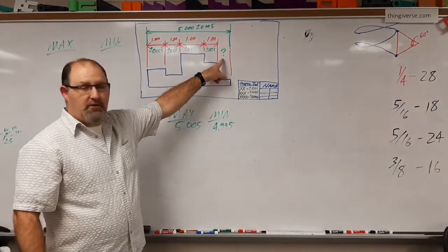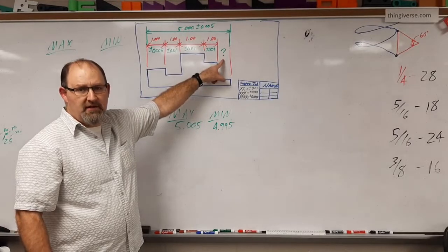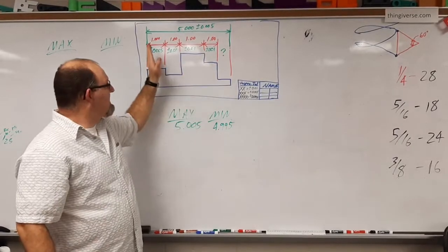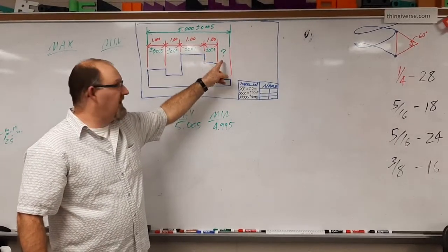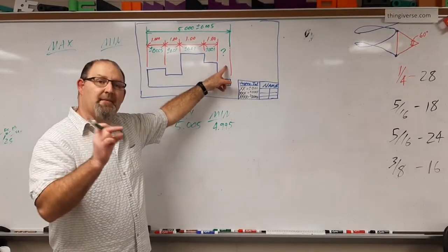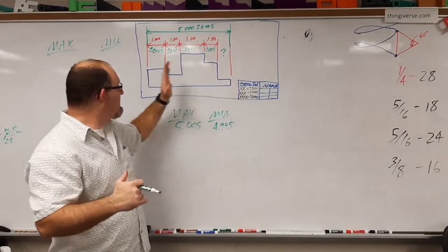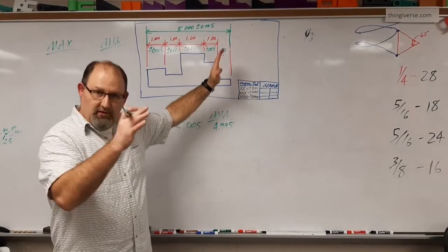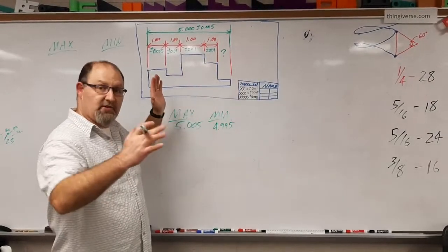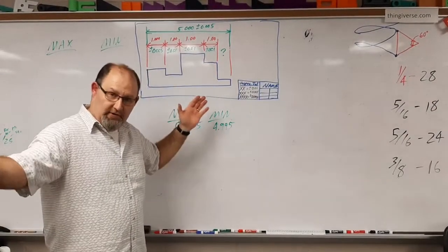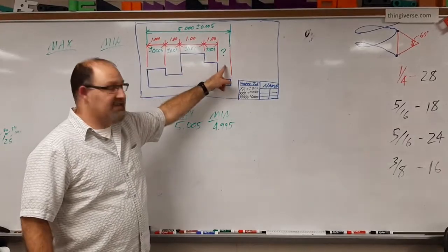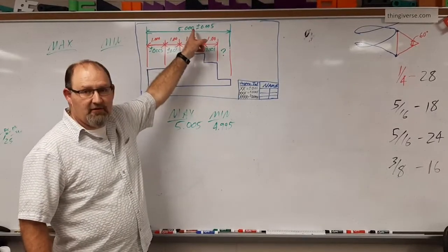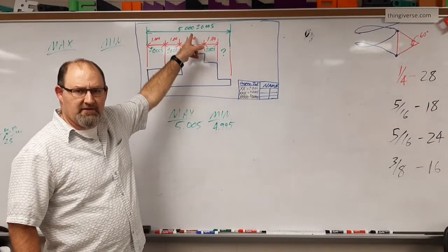We now have, where this question mark is, what we call a runout. Okay, so in this area, this is where all the accumulated tolerances run out. This is now where it becomes the wiggle room. So in the chain dimension style, every one of these was added up or subtracted, and so your runout was at the very end, the total length of the part. In this case, this now becomes the runout because the total length of the part is dictated by another dimension.